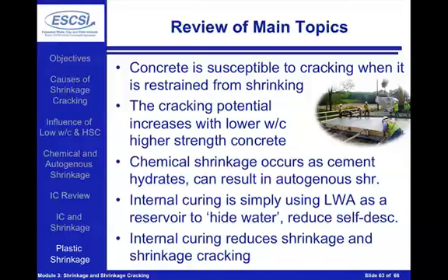So if we can take a second to review, we really want to review the main things that we've seen in Module 3, which was focused on shrinkage and shrinkage cracking. The idea here is that concrete can be susceptible to cracking when it's restrained from shrinking freely. The cracking potential can increase with lower water to cement ratio and higher strength concretes.